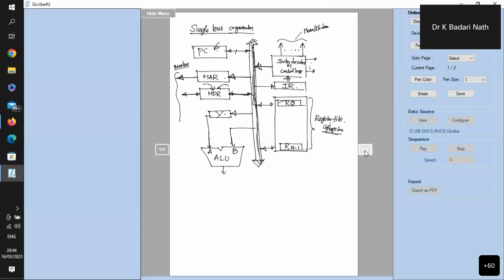Similarly, ALUs are very fast. Within a fraction of a clock cycle, they can finish all your addition and subtraction. We have studied that a CLA adder will take 4 units of time. You should not confuse that with 4 clock cycles. It's 4 units of time, and each unit of time is nothing but the propagation delay of the gates. That means within a clock cycle, all your operations can be completed. The moment you give the two operands, within a clock cycle your addition is also completed, and you should be able to place the data back to the processor.